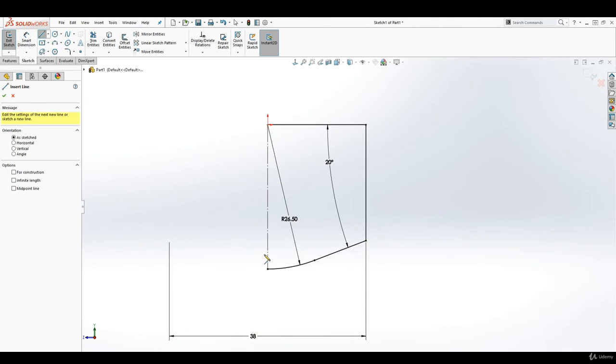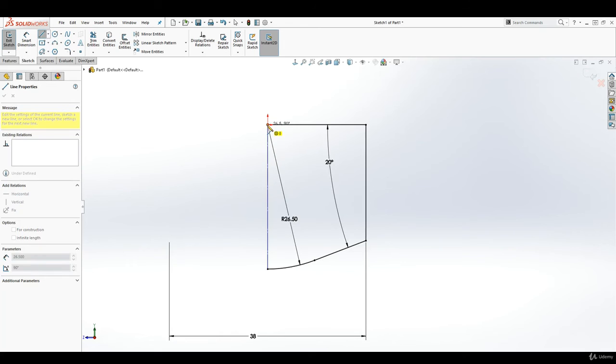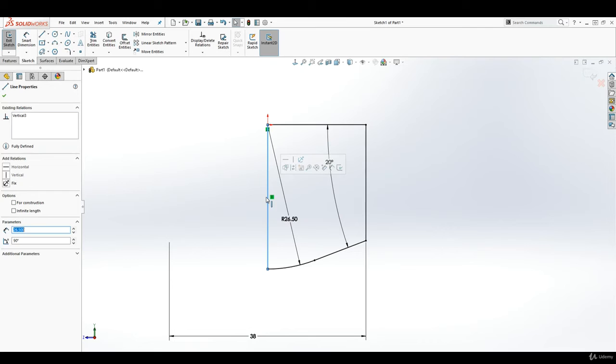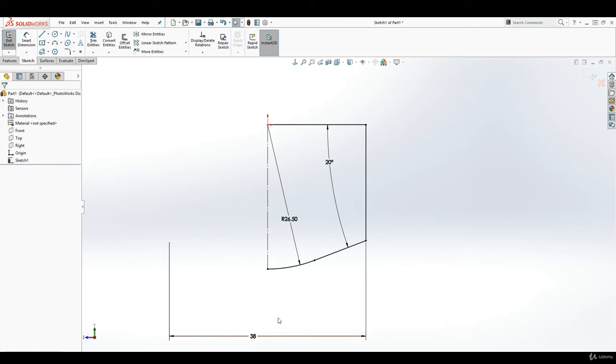And another thing you need to keep in mind is, before you can revolve, your sketch must be closed, meaning you need to have all this sketch all around. The construction line is just something we use. Like I said, you can use it to aid your sketch. I used the construction line to get the 38 diameter.